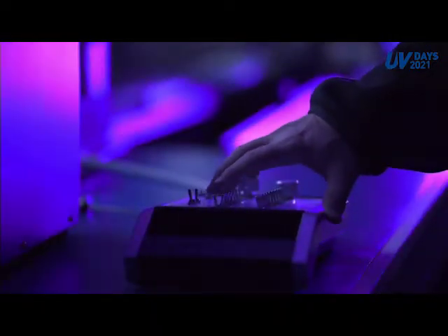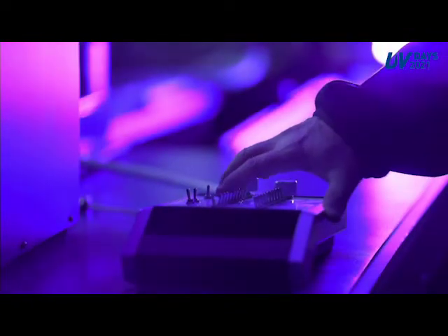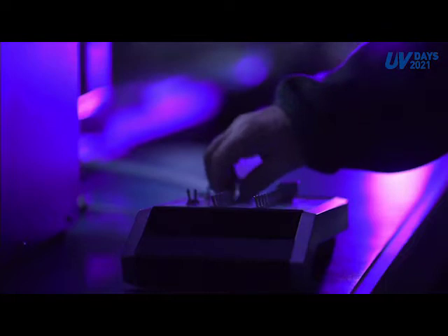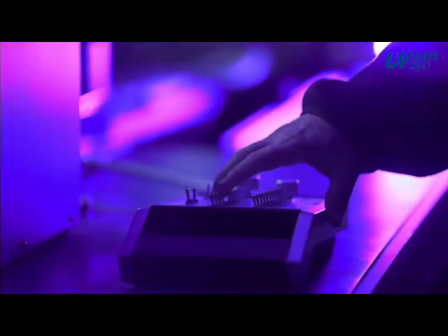For every 1 degree Celsius temperature rise, the UV LED drops 0.5% of UV output. Therefore, 5 degrees would be the equivalent of a 2.5% drop in output of UV from the system. Therefore, a water-cooled system that maintains the diode temperature really is good process control.